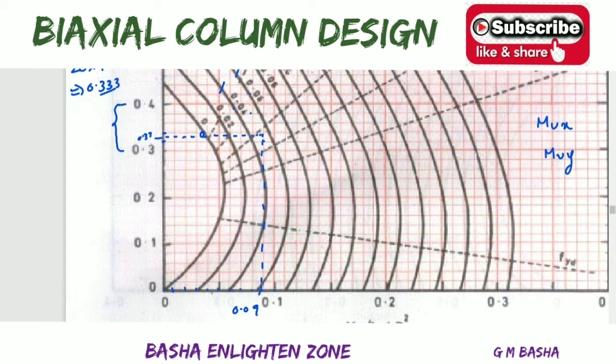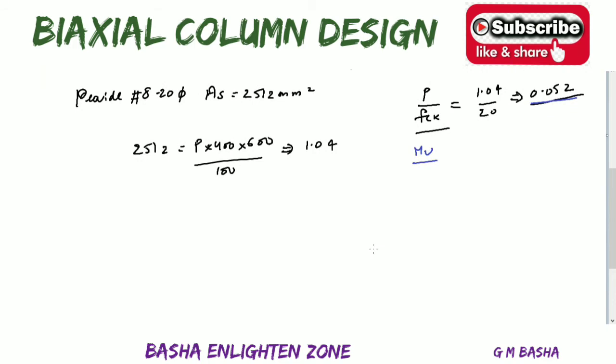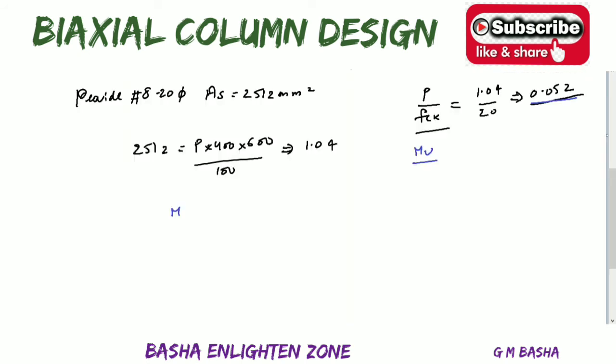You have to choose somewhere in between like this also. If you drop like this, you will get somewhere around the center, maybe 0.085. So there is a chance of the value coming between 0.08 and 0.09. I will show you the difference between both values. If you choose 0.08, what is the value of Mu by fck bd square? It is 0.085 or 0.09. So take down both the values and check the difference.